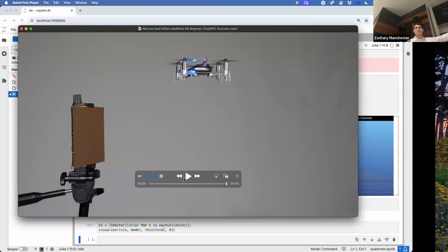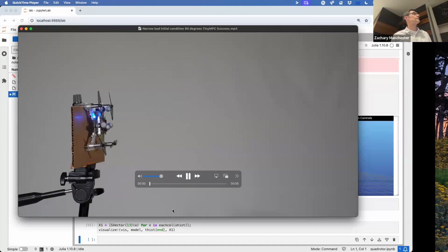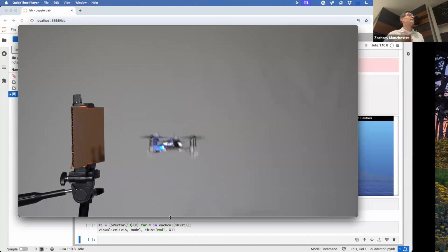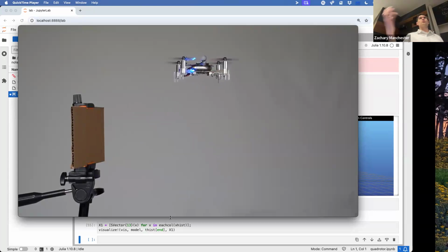So yeah, convex MPC. This is just QPs at 200 hertz on a microcontroller, in real time. We're doing it in mocap, so it's getting the mocap measurement streamed to it, and we're running a Kalman filter onboard that's fusing the mocap with the IMU. But it's pretty vanilla stuff. And again, if you can do this stuff fast enough, you can do pretty crazy stuff on hardware with it. Okay, I think that's all I've got for today.